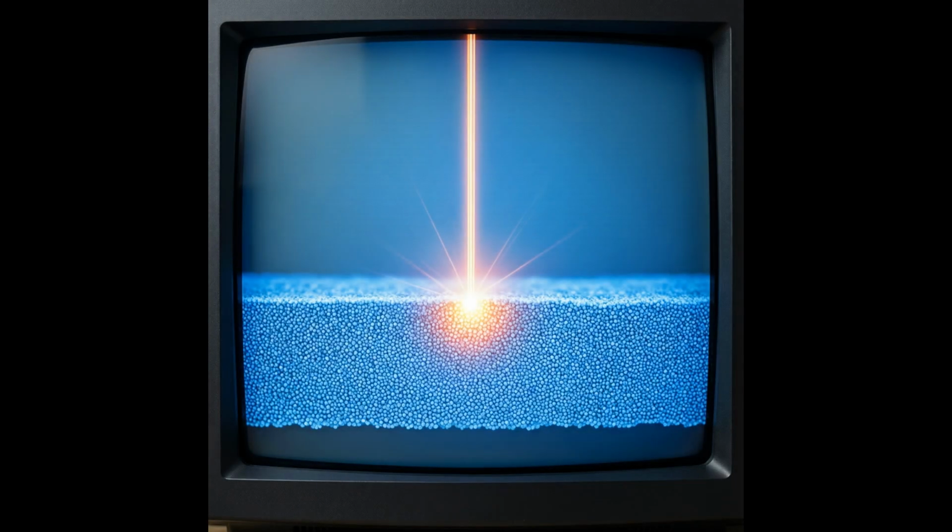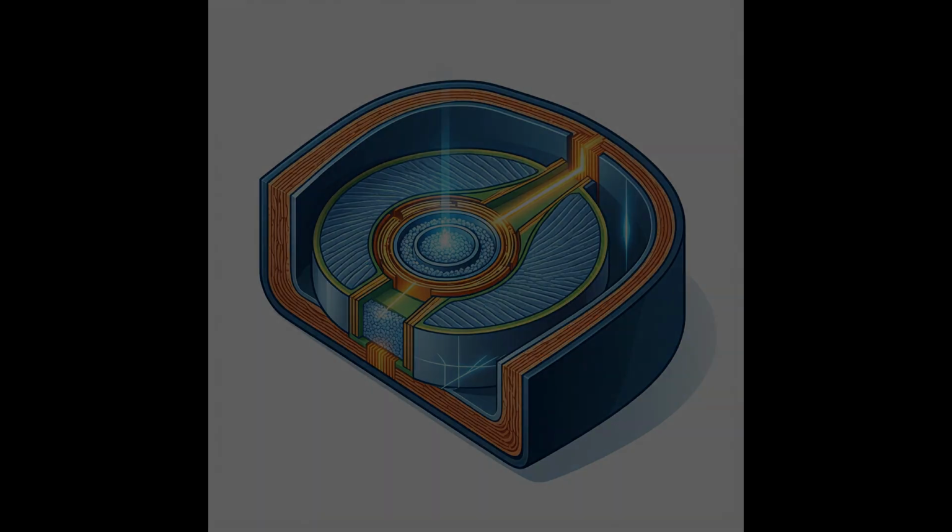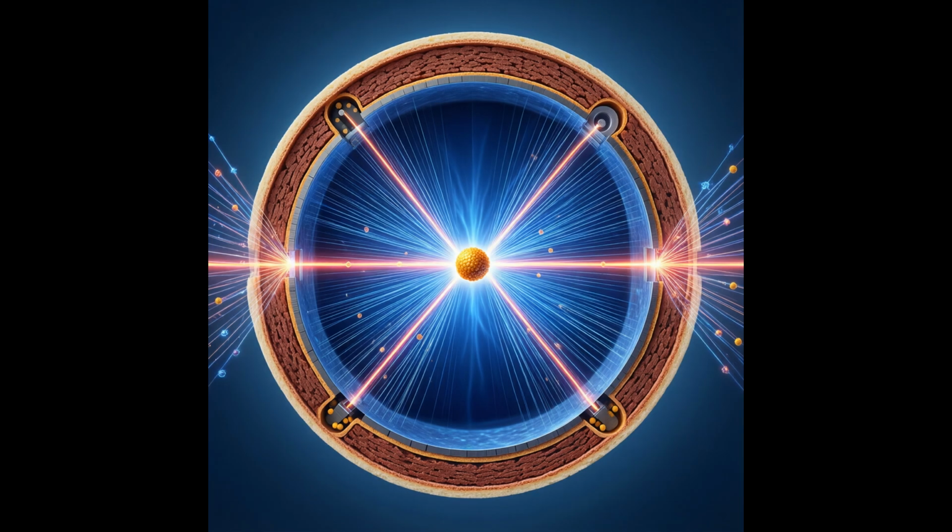The core mechanism relies on a specialized material called phosphor coating applied to the inside of the screen. When high-speed electrons strike these microscopic grains, their kinetic energy transfers directly into the atomic structure. This impact excites electrons within the phosphor atoms, pushing them from a stable ground state into a higher energy orbital level. Because this excited state is unstable, the internal electrons immediately return to their original configuration.